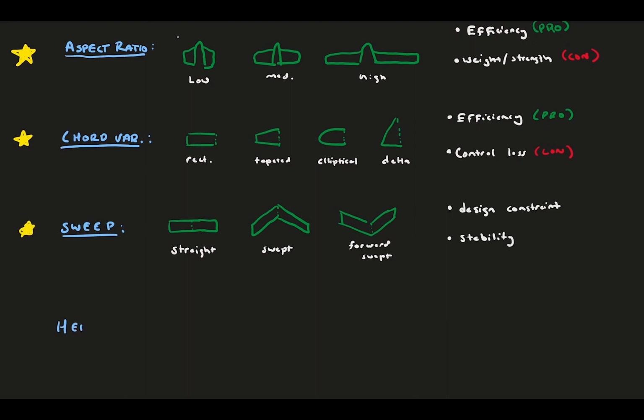And lastly, we can adjust the hedral of the wing, which is a word I just made up. A dihedral wing has the wings angled upwards from a front perspective, and an anhedral wing has the wings angled downwards. Like the sweep, this angle impacts flight stability and control.